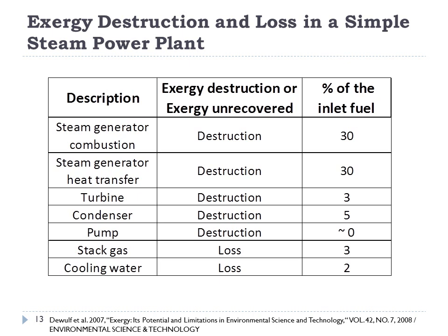So the two main sources of exergy destruction are first the combustion of the coal, which can destroy about 30% of the exergy in the inlet coal, and then transferring that thermal energy from the flue gas, the combusted coal gas, which is nitrogen, oxygen, carbon dioxide, and water vapor. When you transfer that energy to the steam, that destroys another 30% of the exergy originally in the coal.